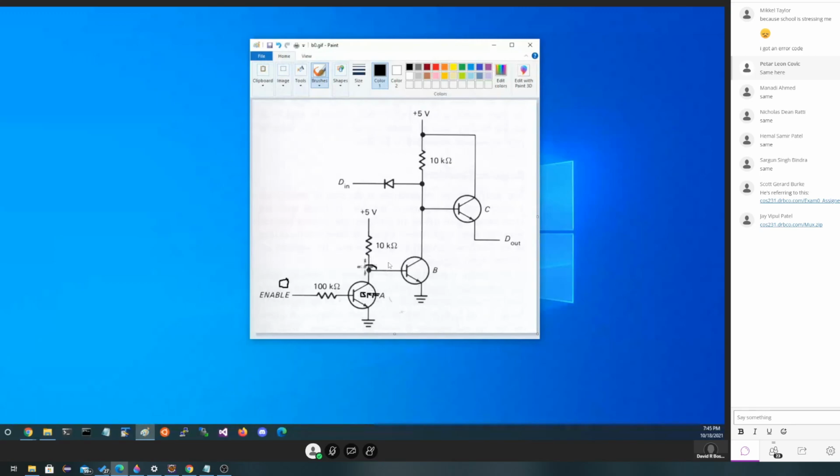What's the voltage right here going to be? 5 volts. Well, think about it. Oh, no, sorry, 0. Well, 0 is down here. How much higher is the base than the emitter if the transistor's turned on? 0.7 higher. Yeah, so we get 0.7 volts right here.